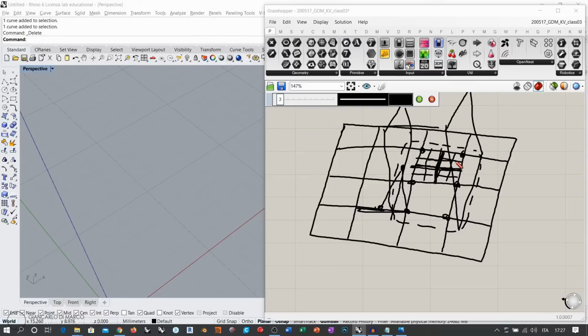But if you do this, you are producing some topological disconnection between this original quad and the neighbors, because you are creating vertices along this edge that don't have correspondence on the other side of this edge. Okay? So the standard mesh representation is not good for producing some differential growth behavior,